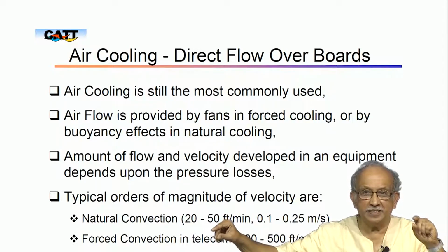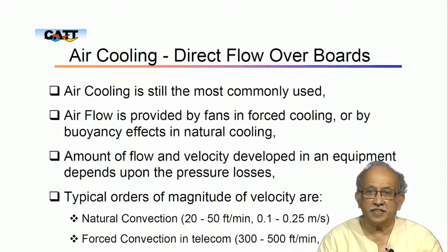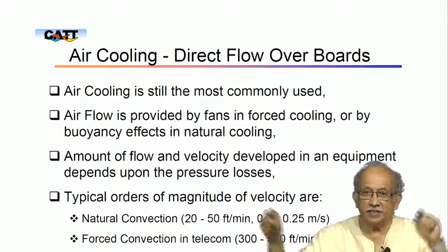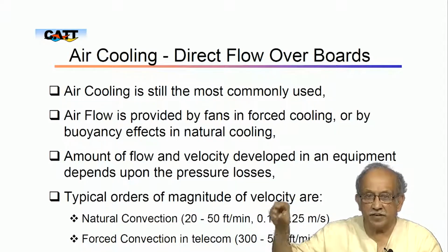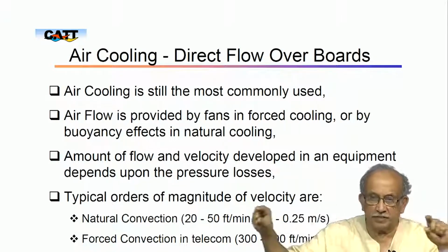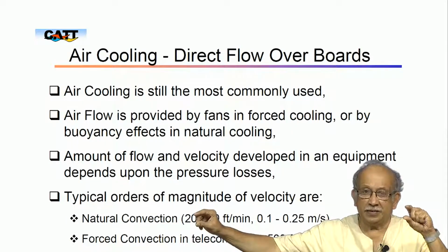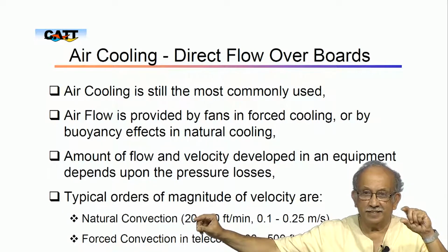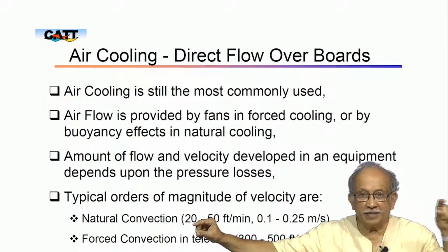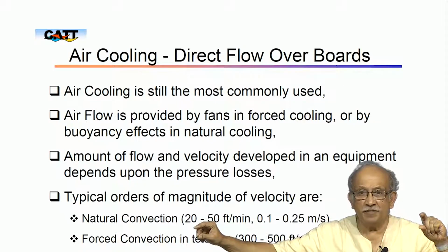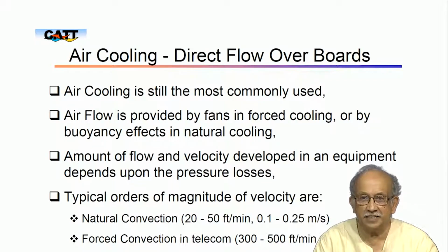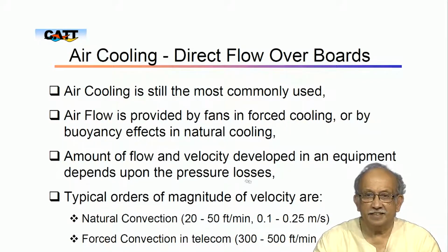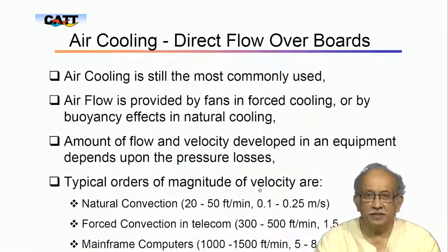And then next, in several places you have features like elbows, valves and all that, where invariably you have a small discharge coefficient. So, if you add all these discharge coefficients and all the pressure drop across the length, and your requirements of how much fluid you want on the other side, it is possible for you to estimate the size of the pump. It is a little like that, which is absolutely no problem.